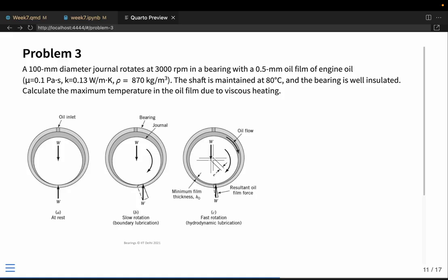This would be very important because of viscous heating. Because the shaft is rotating at a very high speed, the velocity and the Brinkman number will be very high, and you have to select the oil accordingly. One of the main assumptions we have considered here is that properties do not change throughout the flow. We have assumed properties to be constant. If, for example, the oil undergoes some chemical decomposition at some high temperature, then you have to carefully select what material you are using. So it is important to understand the maximum possible temperature that can happen in these circumstances, and then design what oil you want accordingly.